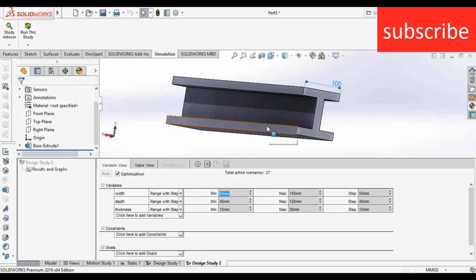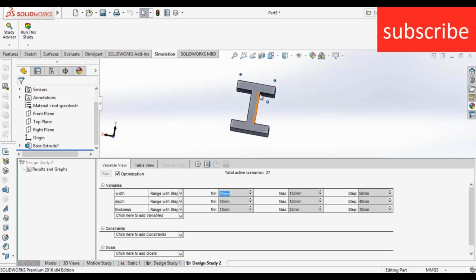What's going to happen when I run the simulation is that it will start with the condition that my width is 50 mm, depth is 40 mm and thickness is 10 mm, and it will run a simulation on these three parameters. Then it will run a simulation where my width is 50 mm, depth is 120 mm and thickness is 10 mm. In this way it will do a permutation-combination like thing, and we get the result.